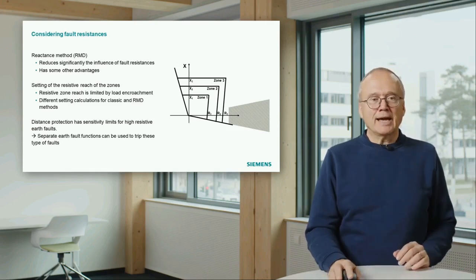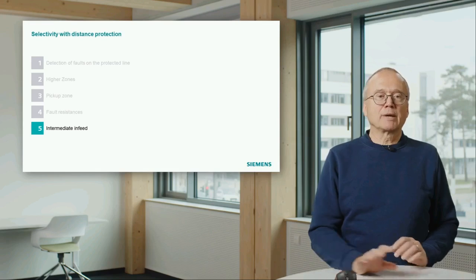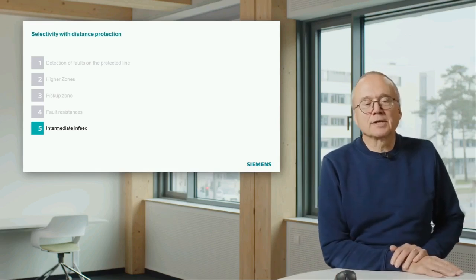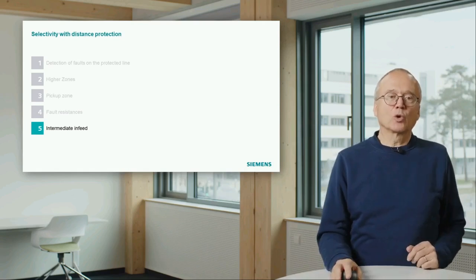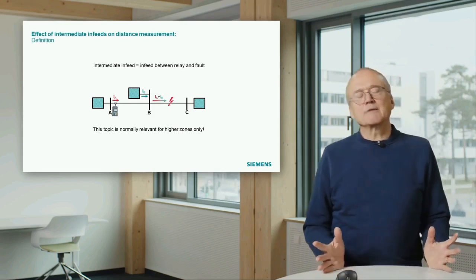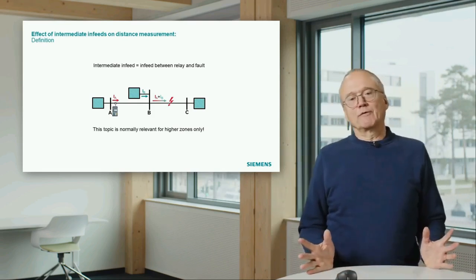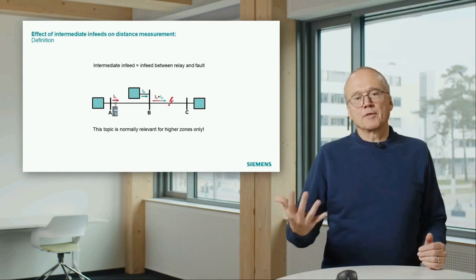And the last thing I would like to mention in the context of sensitivity with distance protection is also an important thing, the role of intermediate infeed. And intermediate infeed is a thing which is only relevant for the backup case.